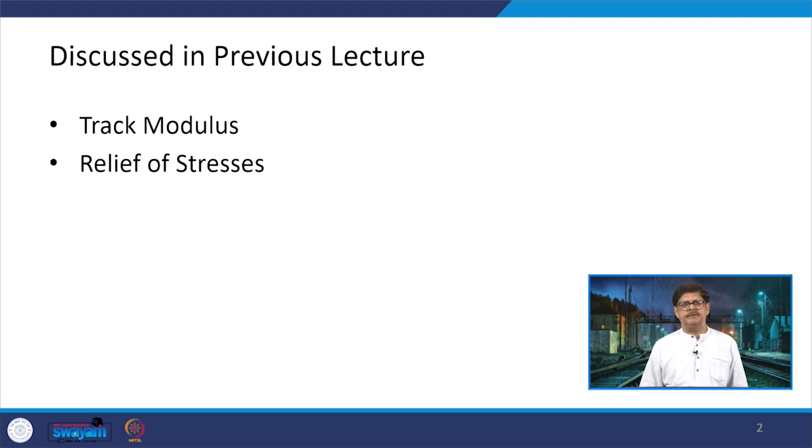So, that was one aspect which we discussed, and then towards the end we talked about the lift of the rail also, where it was discussed that if there is a loose packing, then the stresses which are being caused, the bending stresses, can increase by 10% or even more than 10% if the maintenance is not good.